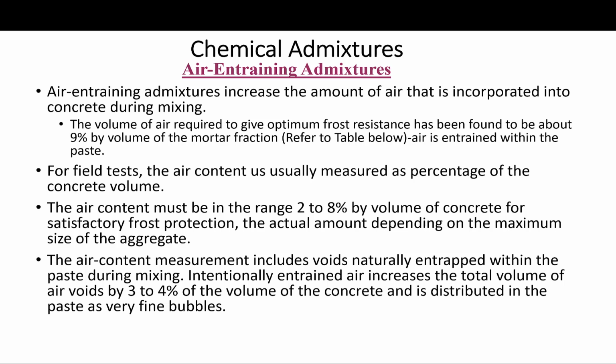The air content measurement includes voids naturally entrapped within the paste during mixing. So the entrapped air is different from the entrained air. The intentionally entrained air increases the total volume of air voids by about 3 to 4% of the volume of the concrete, and it is distributed in the paste as very fine bubbles.